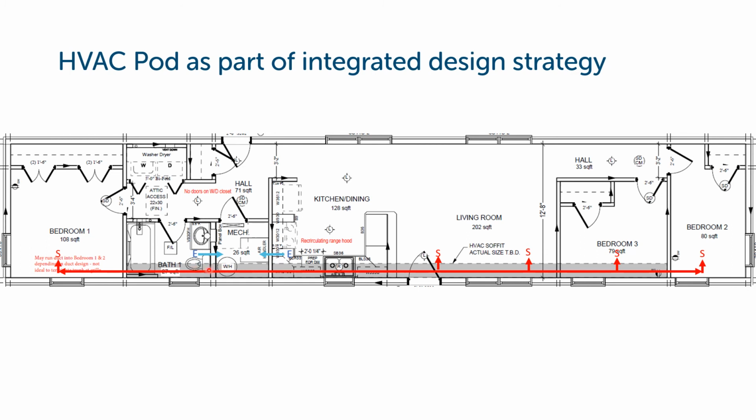The supplies, just as we described, go from the air handler through a small plenum into the main trunk, pick up the injection port on the way to get ventilation air, and then it tees off and goes in two directions. Simple supply. And these are supplies in a soffit that's built between the wall and the ceiling in the upper corner of that wall.